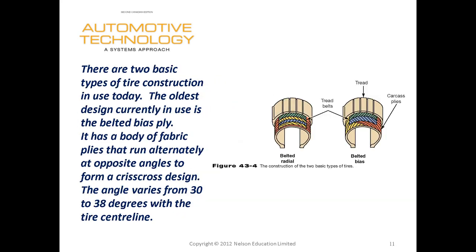A couple different styles of tires, or tire construction. Either we're going to see a radial tire or a bias ply tire. Bias ply tires are way less common. They were kind of the original design. You still can get bias ply tires, more so for trucks, 4-wheel drives, or specialty. Maybe some drag racing tires would be bias ply. Possibly not.